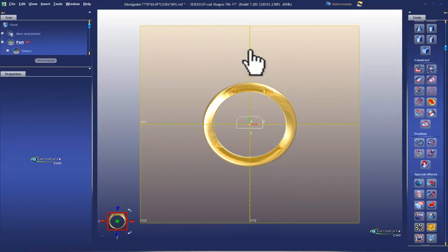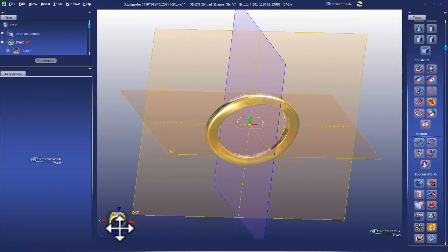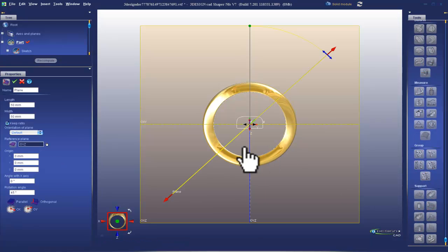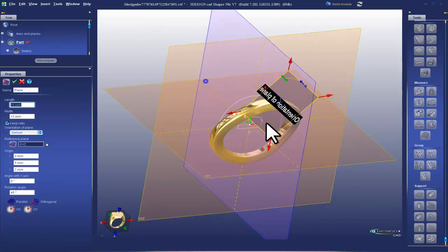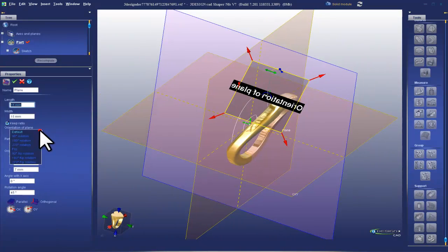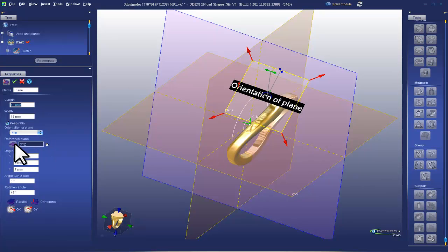You know what? I'm going to put a plane in just to show you how to put planes in. It's down here under support. Bring it up on the Y to maybe 5, and we'll bring it out on the Z to, I don't know, 7. That should give me the cut I need, and we'll make the size of it 15 by 15. And the orientation, it doesn't matter so much for this, but I'll flip it, have it be like so.